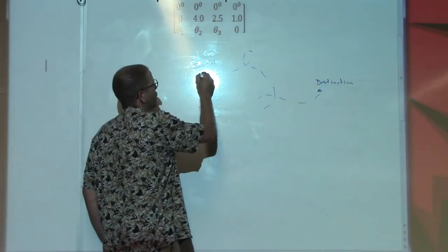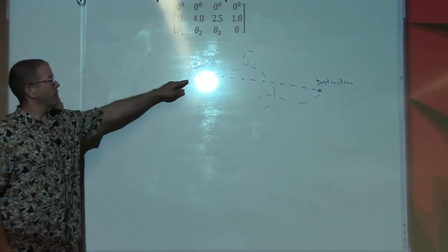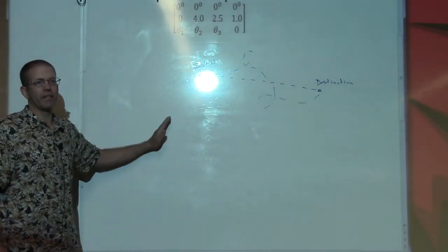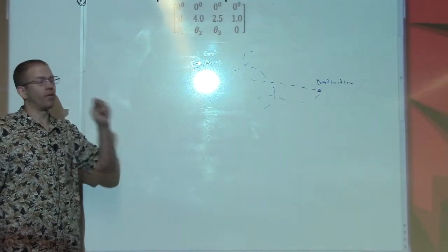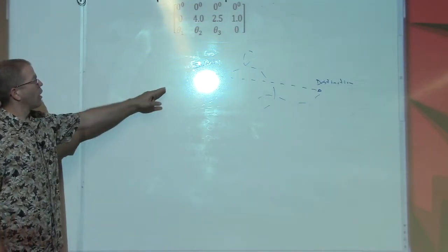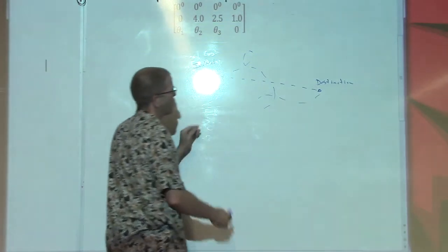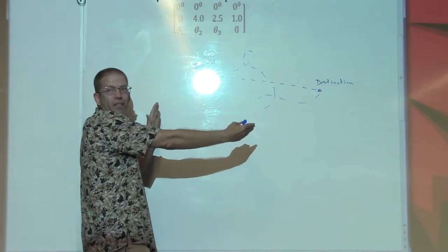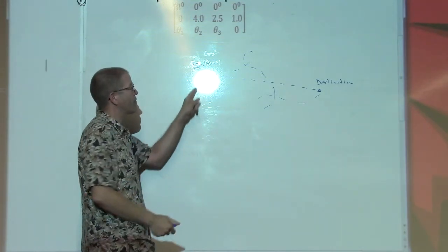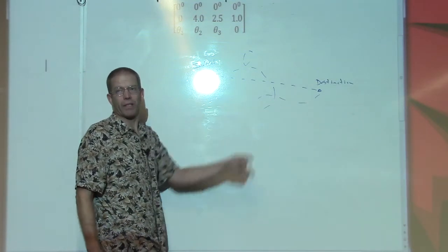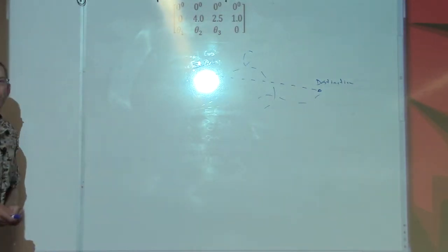So what we're going to do is figure out a way to make that end effector follow a straight line. We don't care what the joints do as long as the end effector is following a straight line, okay? So we're going to interpolate a series of points between this point and this point. That means that we're going to essentially create an equation of a line between the 2 points and follow that line as we move from one point to the next, okay? What's the easiest way we can possibly do this?